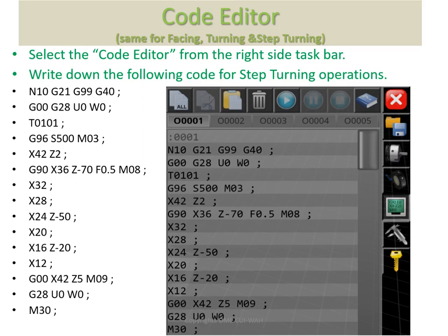The middle part is related to the workpiece details. You will define the workpiece here, like its length, diameter, and which operation you have to perform. All these details will be written here. In the end part, you will close the program, and other things, like if the coolant is on, you will write the command here for switching off the coolant. Similarly, M30, this line, is used to close the program. For writing the program, you can use your own keyboard, and the simulator's option for writing can also be used, which I have discussed in detail in the coming slides.